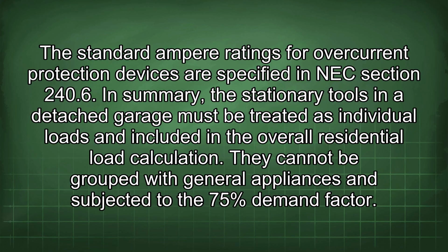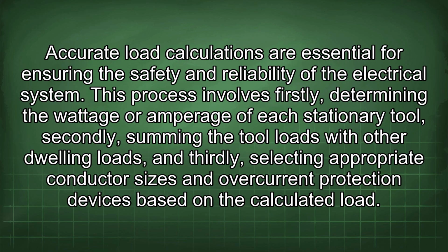In summary, the stationary tools in a detached garage must be treated as individual loads and included in the overall residential load calculation. They cannot be grouped with general appliances and subjected to the 75% demand factor. Accurate load calculations are essential for ensuring the safety and reliability of the electrical system.